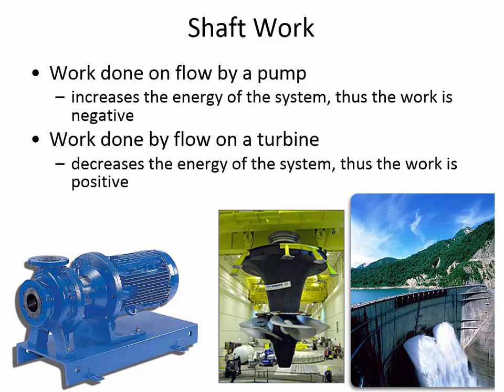So actually, the way that a pump adds energy is by increasing the P. The pressure goes up due to a pump. And so the work that's done by a pump is by increasing the pressure of the fluid. As a cylindrical pump rotates, it's accelerating the fluid and increasing the pressure. And then, like we were saying, what you actually see with your eyes is that now the water is shooting out of the pipe more quickly. It's because of the increased pressure at location 2 compared to what it was before. It's that pressure increase that causes the velocity to go up. So it's a cause and effect relationship.